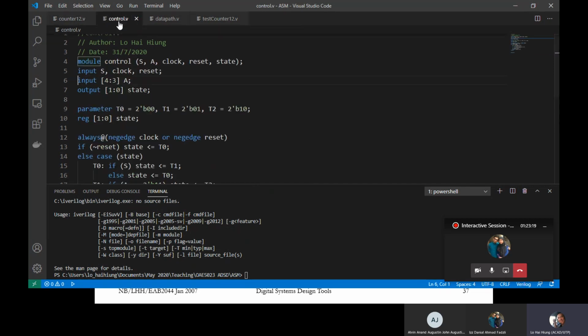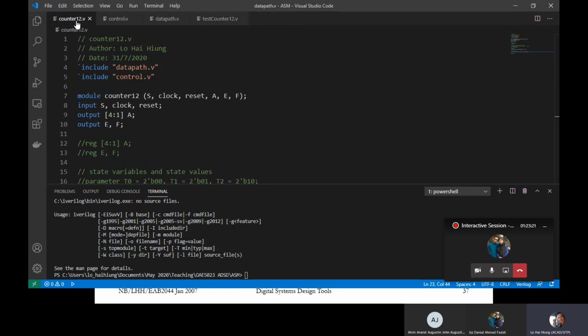If you are splitting your design into multiple files and you do not want to type a very long iverilog compile command, you use the include pre-processing directive. It will tell the compiler to look for this file and that file. So I include two separate module files.